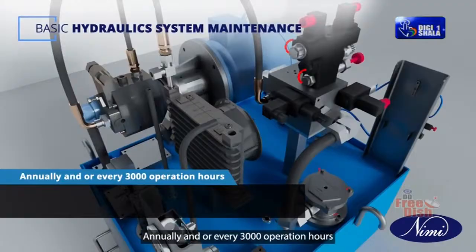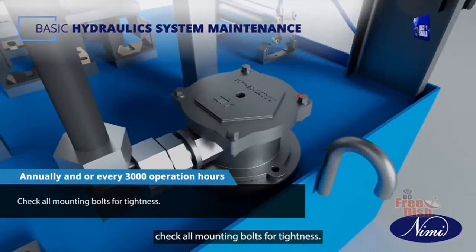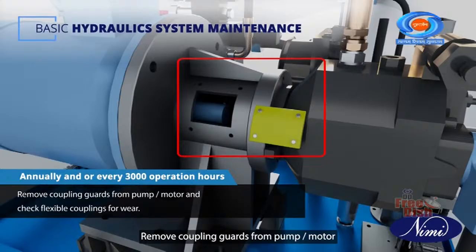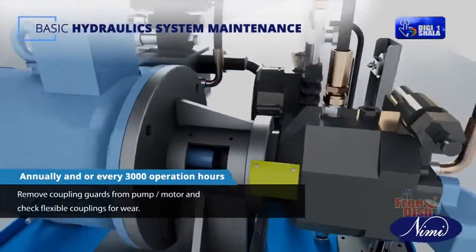Annually and/or every 3000 operation hours, check all mounting bolts for tightness. Remove coupling rods from pump or motor and check flexible couplings for wear.